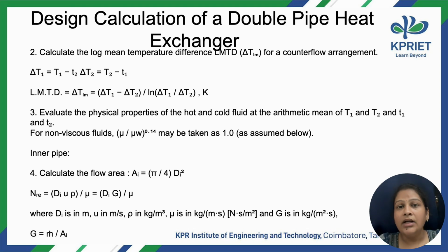So basically, when we want to find out the heat transfer coefficient for any fluid flowing in the pipe, we'll be going for either the Sieder-Tate equation or the Dittus-Boelter equation. This usage highly depends on the values of Reynolds number and Prandtl number, so it is important to find out this Reynolds number and Prandtl number. And one more important step to be noted is that in most cases in your problem or in the design calculation, the velocity of the fluid will not be known.